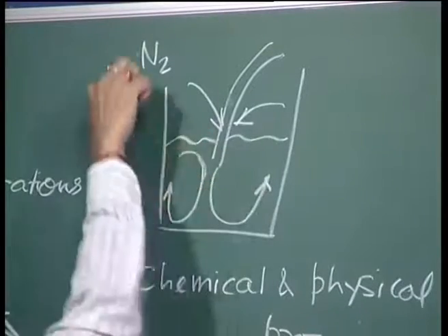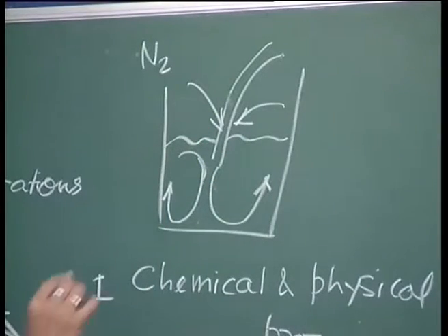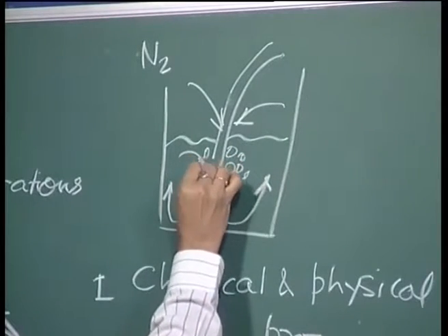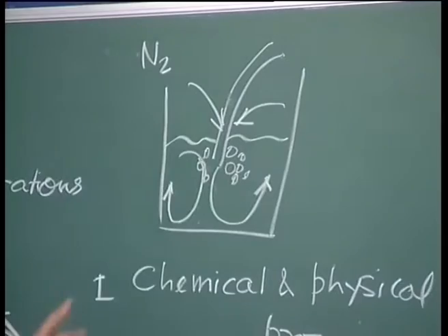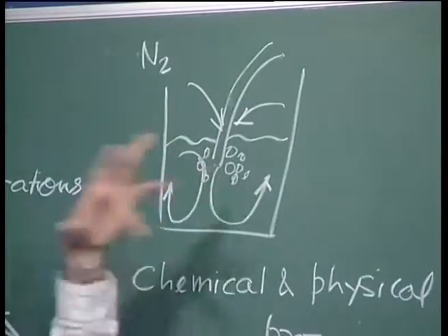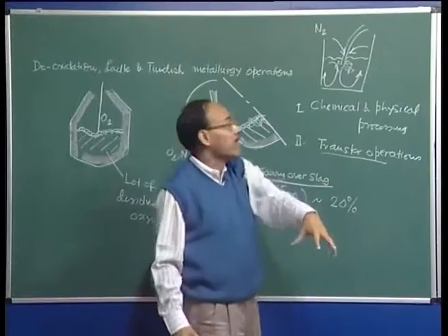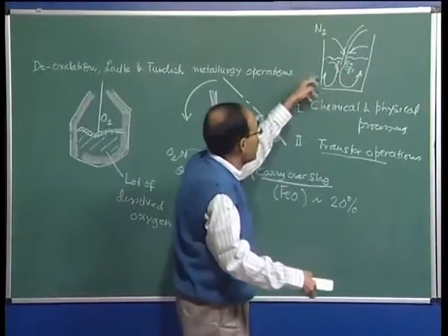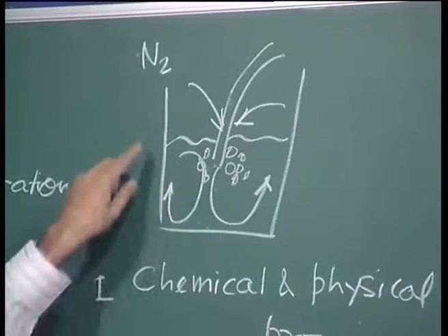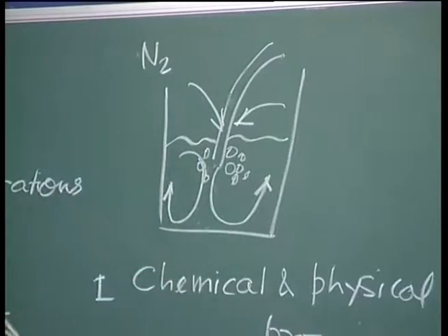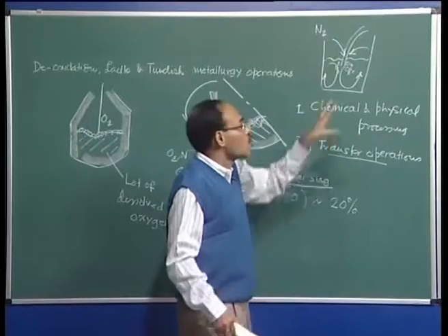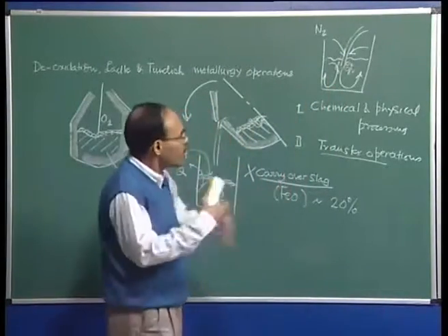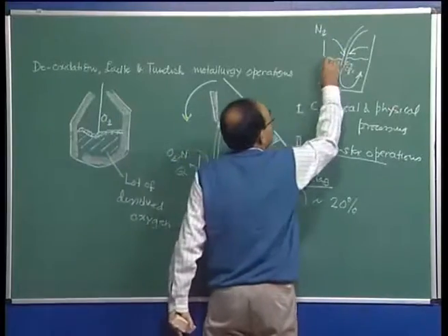We can have some nitrogen and hydrogen which can be absorbed by the tapping stream, and one can really see that there is a lot of air entrainment. What happens is that when this jet, which we say is an impinging jet, strikes the ladle, it moves in a counterclockwise direction, and this rotation is at an extremely high speed. So, whatever we have added here to make the fresh slag gets dissolved or melted very quickly and instantaneously.